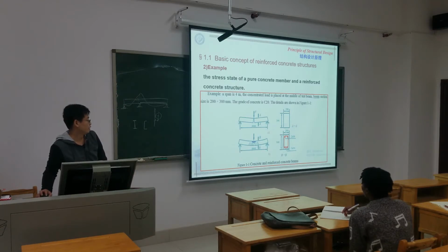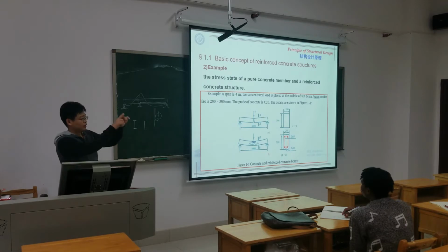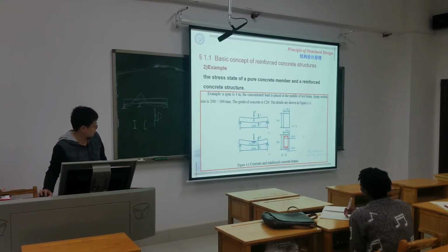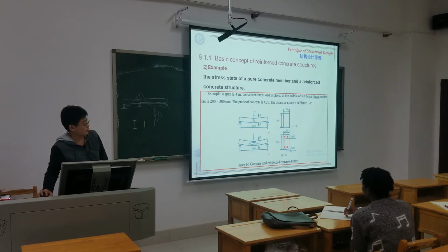So actually these are mainly put here because of the structural requirement, not from the design, not for the calculation of the force. It's just to make this stable skeleton. And the most important things are this longitudinal steel and also the stirrup.